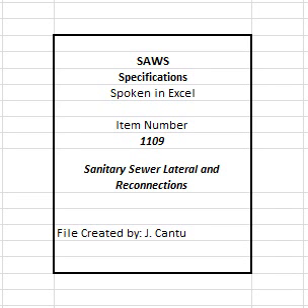The SAWS construction inspector reserves the right to require service connections by excavation when a remote cut service connection damages the sewer mains or lateral lines. Open cut excavation for service reconnections on CIPP will only be allowed if it has been approved in writing from a SAWS inspector. G. The inspector reserves the right to require service connections by excavation when a remote cut service connection damages the main or laterals. H. Reconnection by the excavation method shall include the stack and fittings and required pipe length, up to 10 linear feet, to reconnect service line.